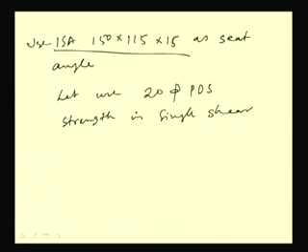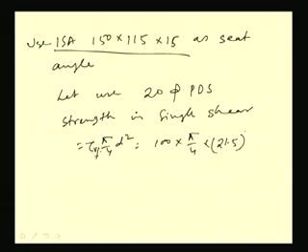So, strength in single shear will become tau Vf into pi by 4 d square. That means, for power driven shop rivet, tau Vf will be 100 MPa, pi by 4, and 20 mm diameter has been used, so the gross diameter will become 21.5. From this we are going to get 36.3 into 10 to the power 3 Newton, or 36.3 kilonewton.